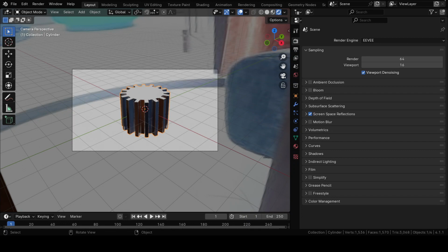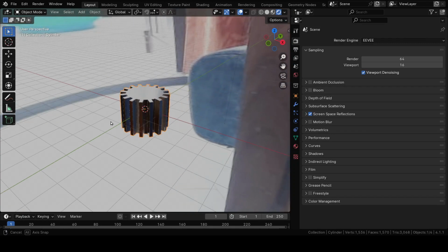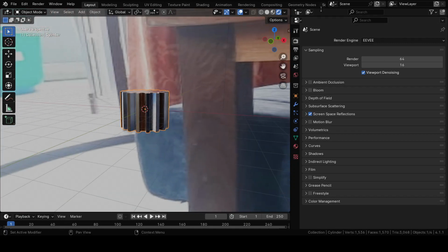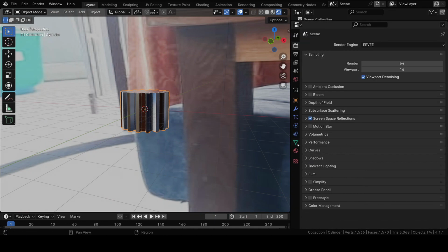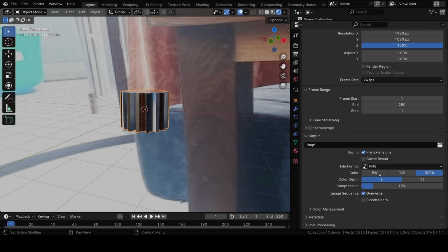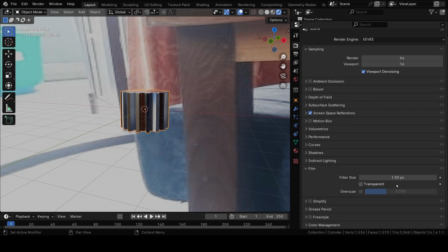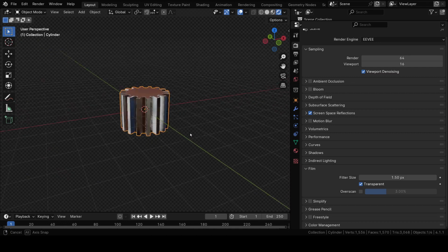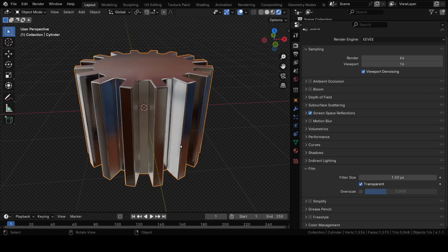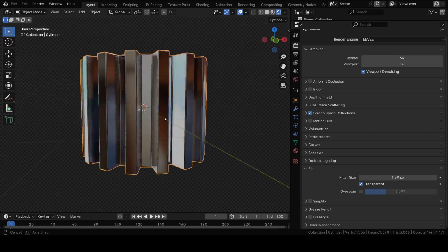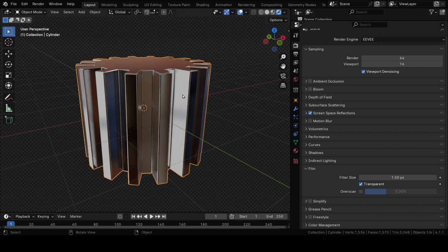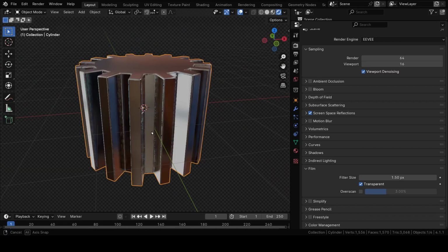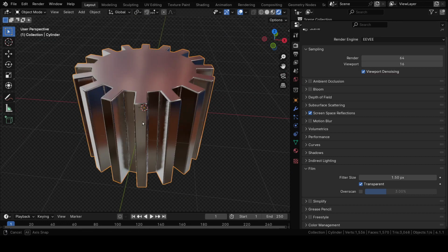Okay, now for you, you won't be able to see. Now I don't want this image, so what we should do is go to render settings and switch on Film Transparent, so that we won't see the world image, but we can see the reflection of that image on the object. Yeah, that is one advantage. This is one way of lighting.